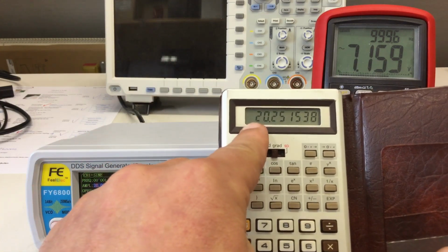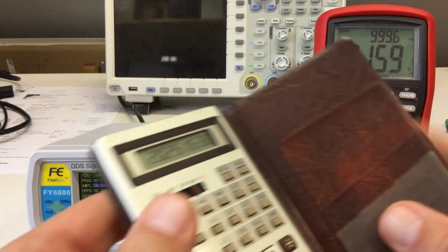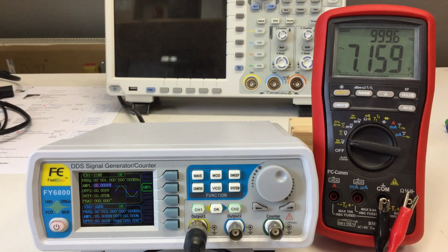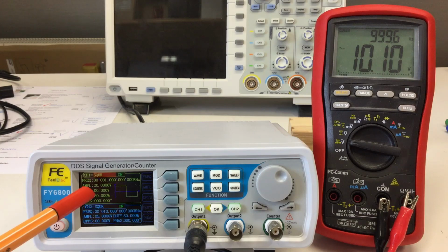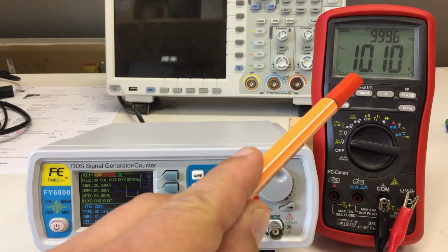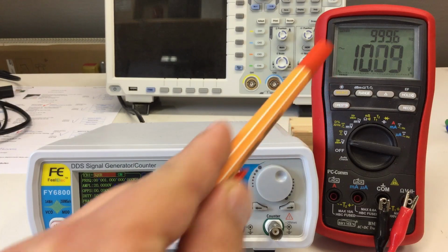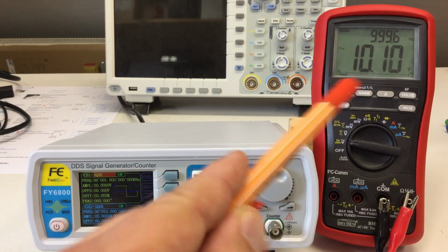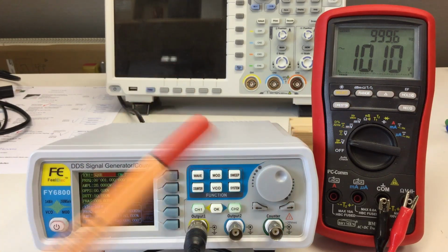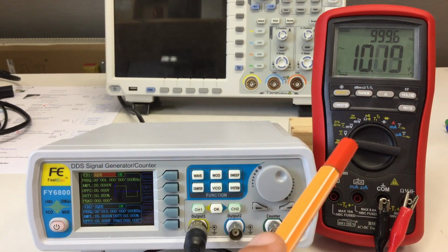We saw the formulas of 20.25 volts. So that value times 2 times square root of 2. So we are spot on. And for a square wave with 20 volts peak to peak, we measure an RMS value of 10 volts. Let's say 10.1 volts. And the formula multiplied that by 2. So we are measuring 20.2 volts peak to peak. Also quite okay for that kind of function generator and that kind of instrument.